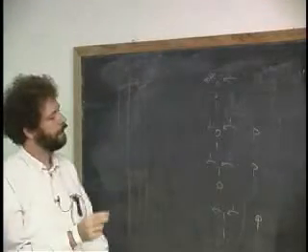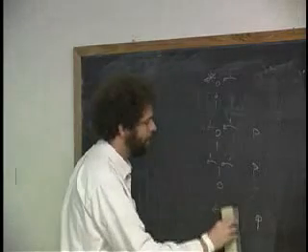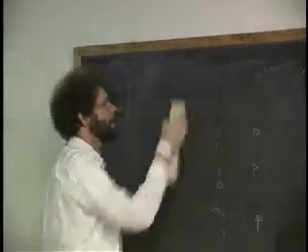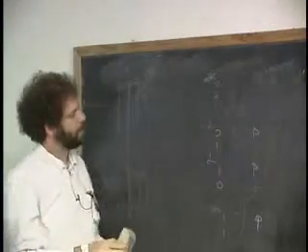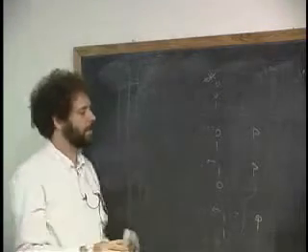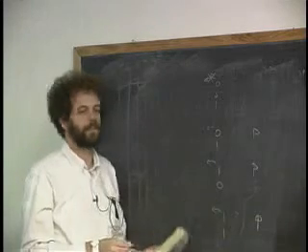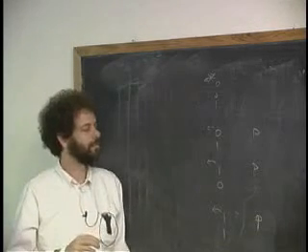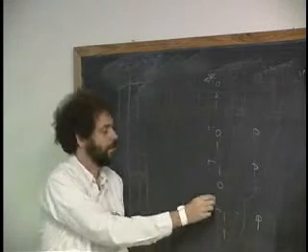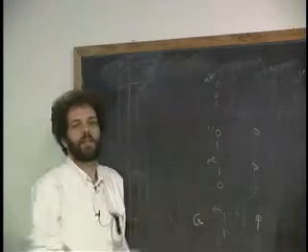Okay. Second question. Independent of what the carry-in is, let's say I don't worry about that. I only worry about these bits here. Assuming that the propagation is handled in a separate way, in which cases here do I generate a carry, irrespective of what comes in? Here, no. Here, no. Here, no. Here, yes. Okay. So here I generate, and in those three cases I propagate.